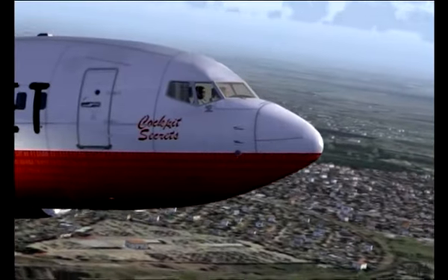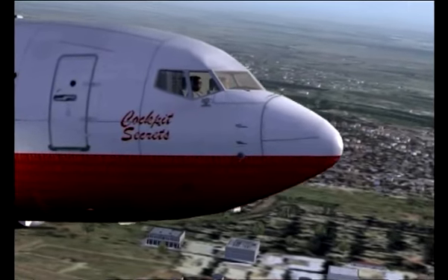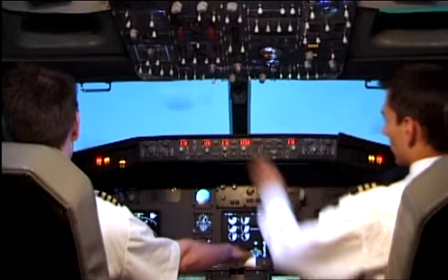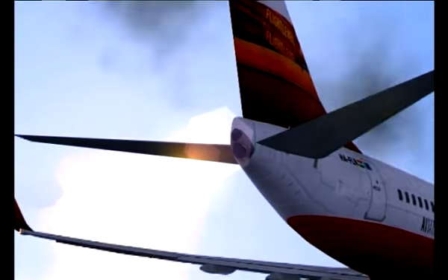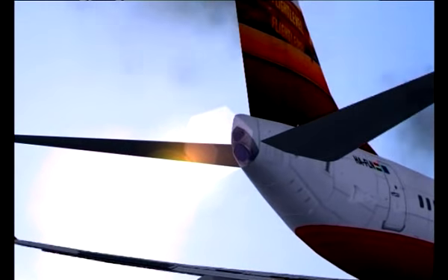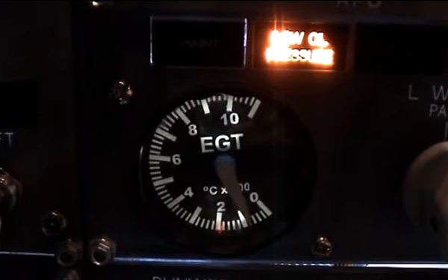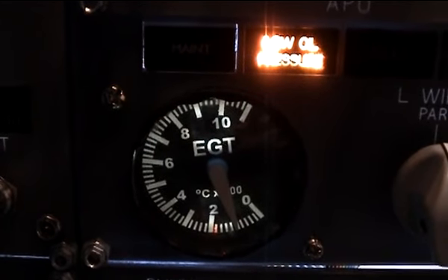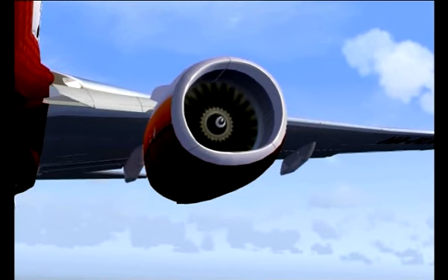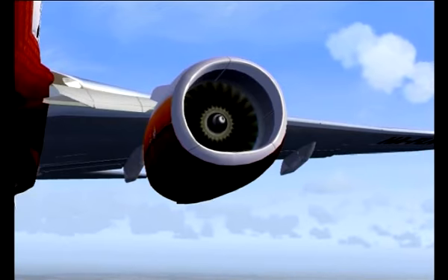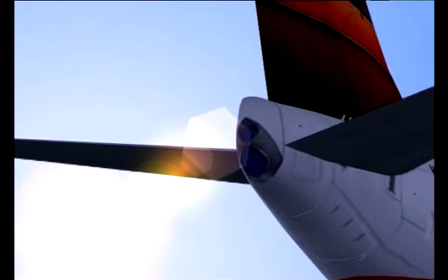At a safer altitude, the cockpit becomes a really busy place. Set. Start APU. APU stands for Auxiliary Power Unit, and it's a small jet engine in the tail of the aircraft. It does not move the airplane, but generates electricity and compressed air. In normal conditions, the APU is not needed in the air, because each of the two main engines can generate enough power. With a failed engine, however, only one generator remains operative, so the APU has to be started as a safety backup generator.